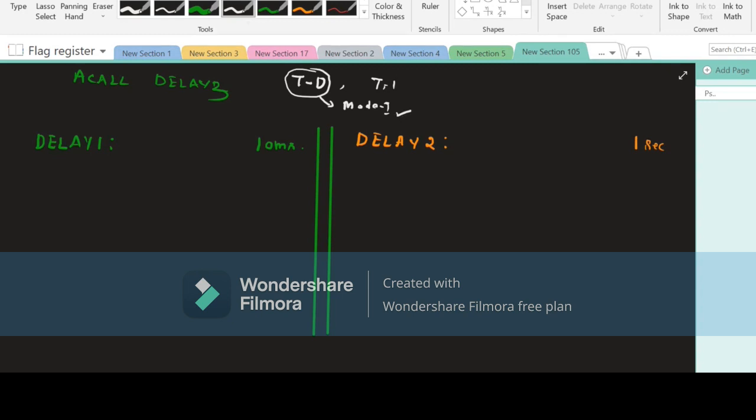If you remember, to work in serial bit transfer, we need our timer to be working in mode number 2. So remember this: if you want to transfer some data serially, mode number 2 is important. And if you are creating a delay, then we want our timer to be in mode number 1. So now how do we set that our timer will be in mode number 1 or 0? For that, we all know a very simple thing: we have to write this program.